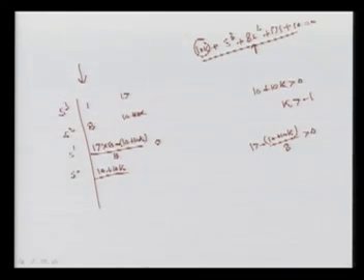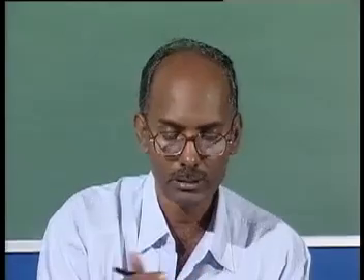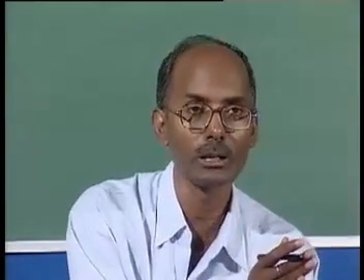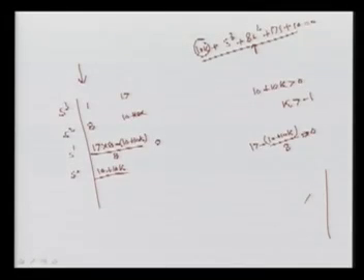Let us suppose for 0, what the value is. 0 means we are at the axis. If it is not 0, it means we are just below this imaginary axis. Here, as I said, we are at the crossing. So if k value is less, if it is positive, then we are here somewhere, but if it is 0, we are here. If it is more, it means sign change and the system is unstable. So for 0, we can calculate, multiplied by 17 into 8, this is 136 minus 10k is equal to 0, or you can say k is nothing but 12.6.